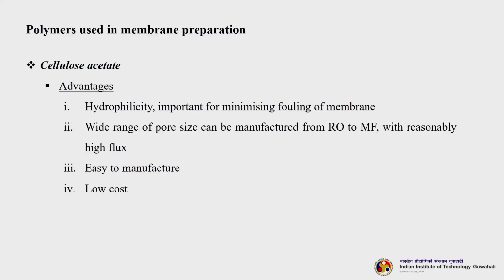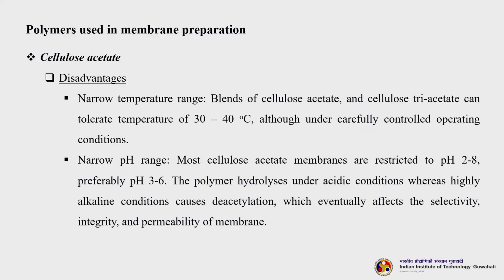Now, the advantage is hydrophilicity. So, the more hydrophilic the material is, the less the fouling will be. So, a wide range of pore sizes can be manufactured, from RO to microfiltration, with reasonably higher flux. It is very easy to manufacture and the cost is of course low. But it has certain disadvantages also.